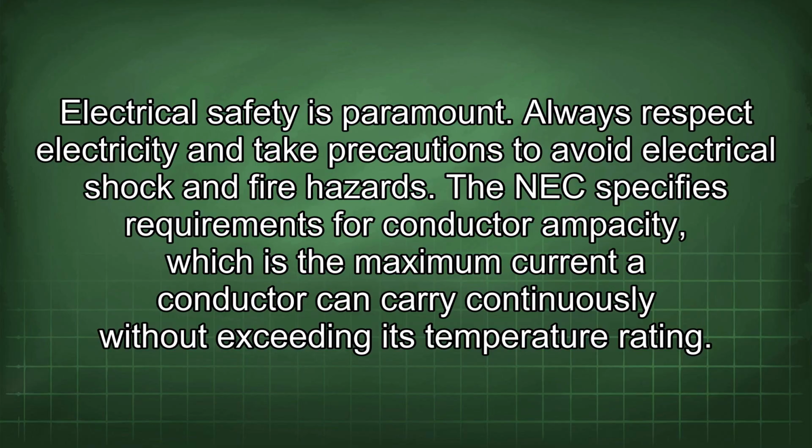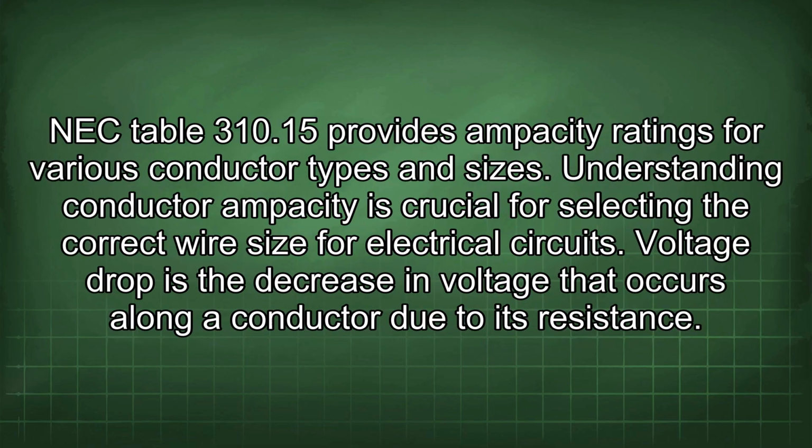NEC specifies requirements for conductor ampacity, which is the maximum current a conductor can carry continuously without exceeding its temperature rating. NEC Table 310.15 provides ampacity ratings for various conductor types and sizes. Understanding conductor ampacity is crucial for selecting the correct wire size for electrical circuits.